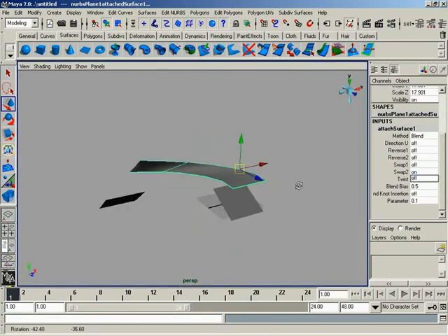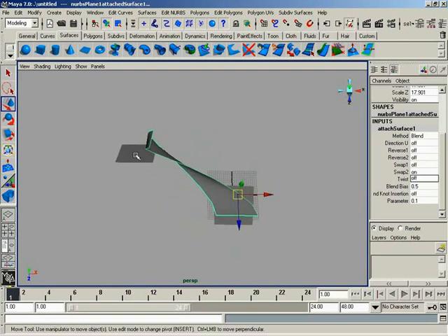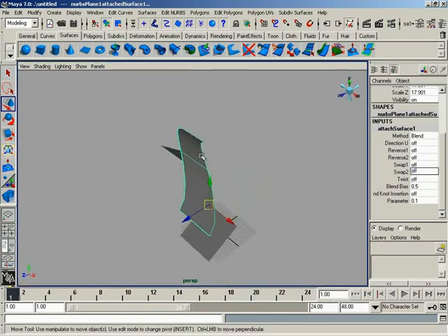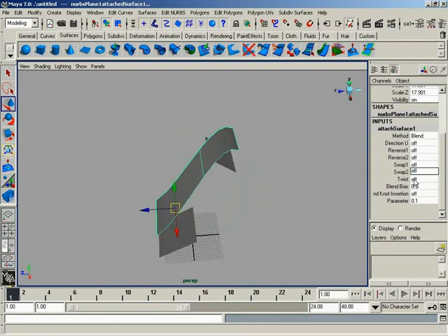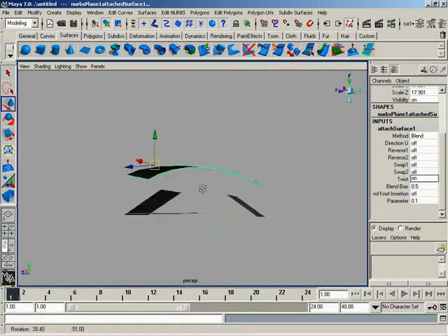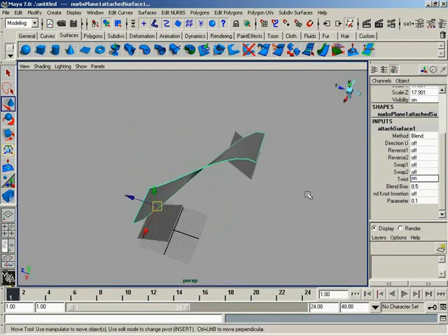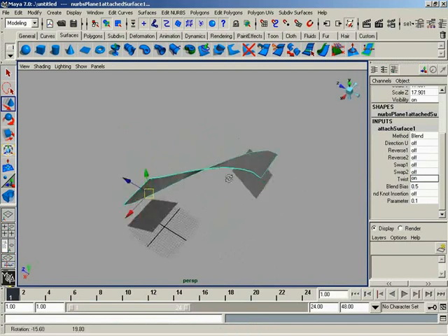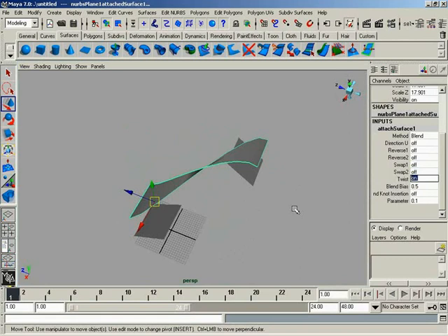So it's just kind of another way to look at surface creation. Let me go ahead and switch off the swap here. So now I have twist off here, and I can switch it on, and notice how we get a twist right in the middle. Usually, I use this as a corrective force, because sometimes when you attach, you may end up with a twist in the middle, and so you can use this as a way to kind of kill that off.